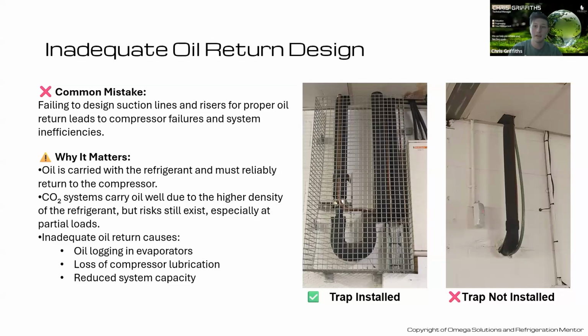With CO2 condensing units nowadays with rotary compressors, they don't hold a lot of oil inside them, if any. So you'll find that oil migrates out of the condensing unit, away from the compressor, and finds its way to the evaporator. They'll normally have control systems in place now so that every so often the condensing unit will talk to the evaporator's expansion valve controller. It will tell that valve to open completely, allow all the liquid to flow through and carry that oil, displace it, and take it back to the condensing unit.